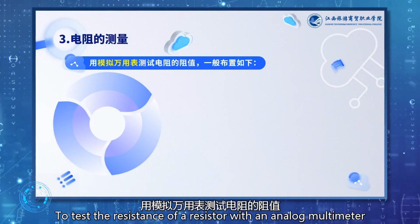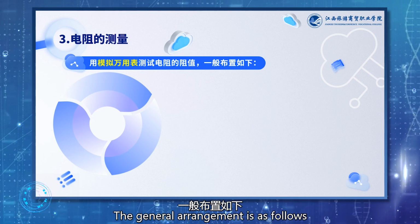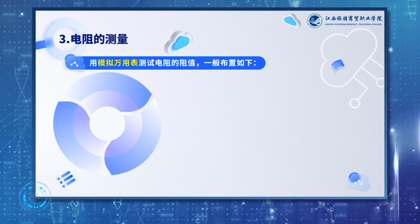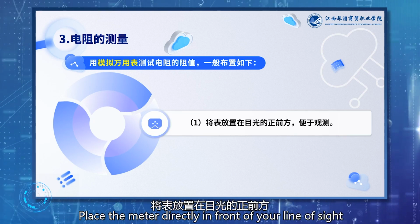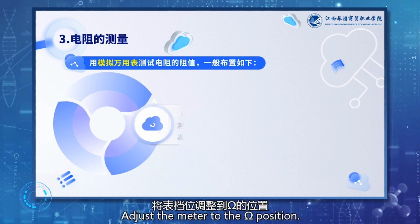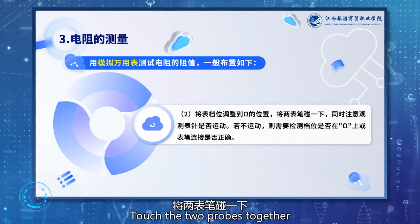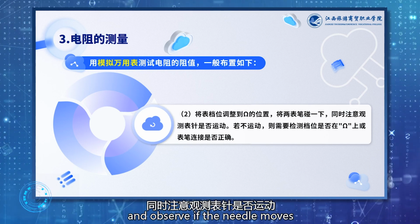To test the resistance of a resistor with an analog multimeter, the general arrangement is as follows. Place the meter directly in front of your line of sight for easy observation. Adjust the meter to the ohm position, touch the two probes together and observe if the needle moves.